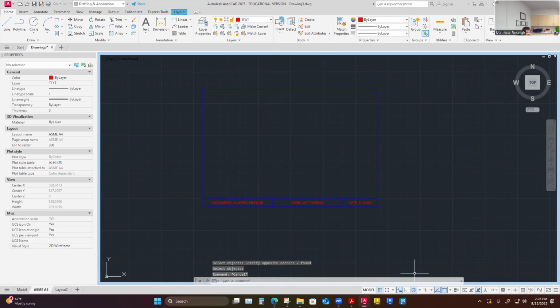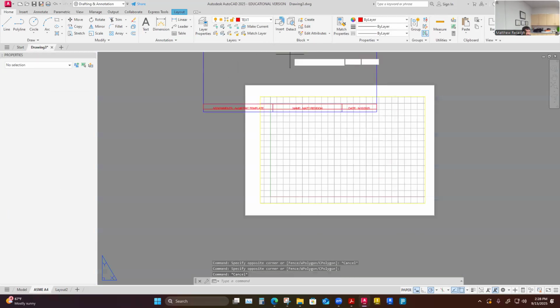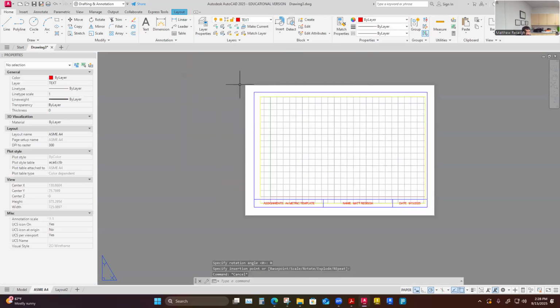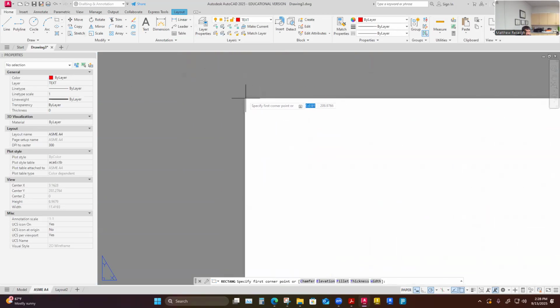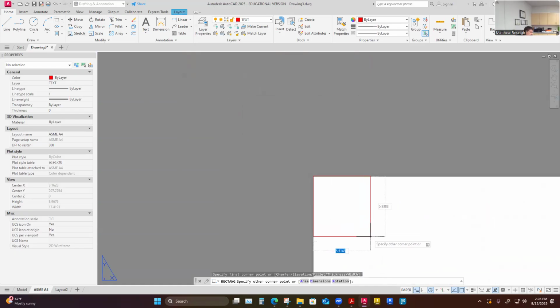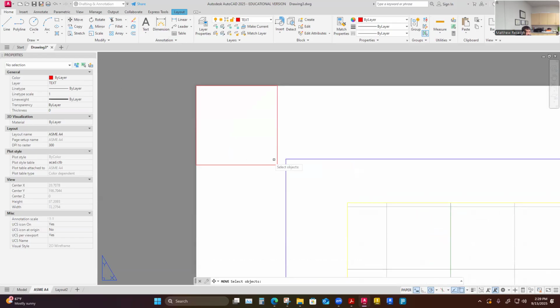Jump back over to this, out to the window here. Can't see that I've done anything, but this is a great place to place it in paper space. So click out here and let's insert this block. And then I'll just do a quick alignment. 12.7 by 12.7. This is also metric out here as well. All my inputs will be in millimeters. Move this.